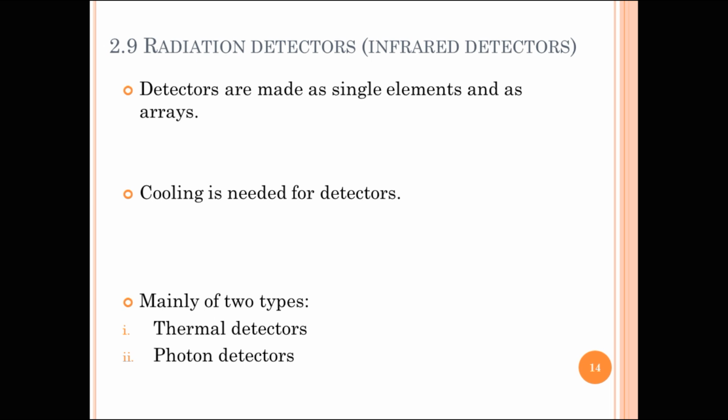The somewhat complex moving parts are done away with in this staring type of imager, where a rectangular array of microdetectors forms the target picture by electronically interrogating each pixel in the array in a sequential manner.